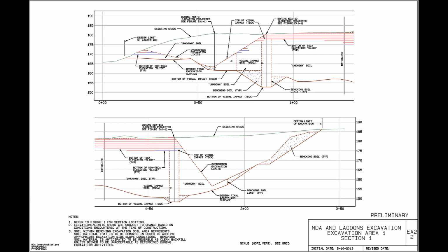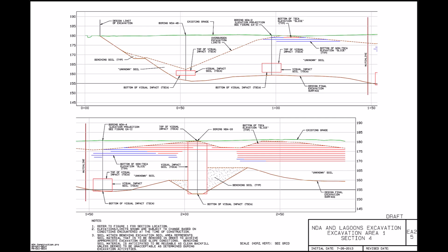Those surfaces were then loaded directly into GPS-equipped computer-guided excavators and bulldozers, providing operators with real-time positional data relative to predefined excavation boundaries. This eliminated field-level decision-making, reduced work interruptions, and enabled optimal segregation of two distinct waste streams throughout the excavation sequence.